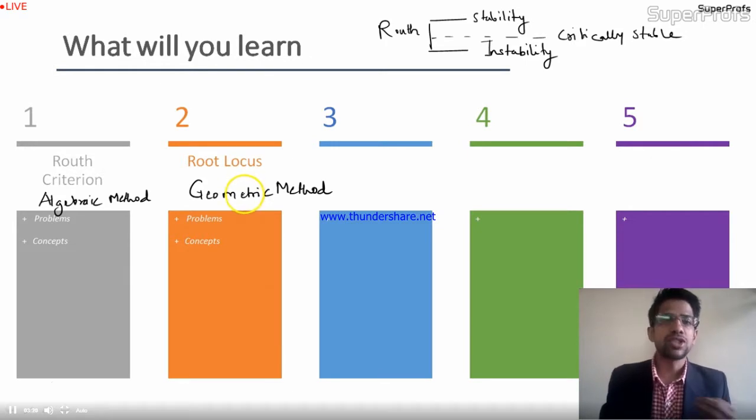As you change one of the parameters, the root locus diagram changes, and accordingly you can decide whether changing the parameter makes the system stable or not. The root locus method is more insightful, and visually it is possible to see if the system is stable or not.